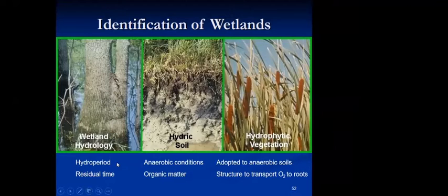That looks at the supporting system, but as a technocrat, as an engineer, we always think of producing or discussing identification in a very specific way, that is, with quantitative and qualitative information. Broadly, one can identify wetlands based on hydrological characteristics, that is wetland hydrology, linked to hydric soil characteristics and vegetation. When all three of these are fulfilled, one can identify it as a wetland.